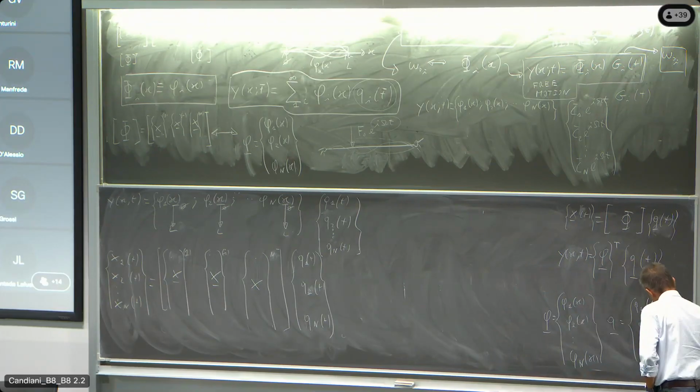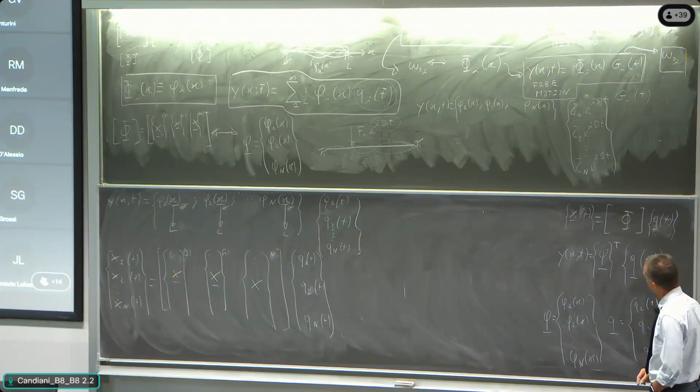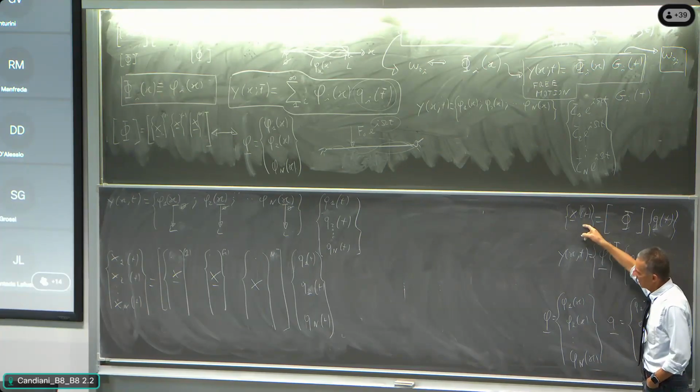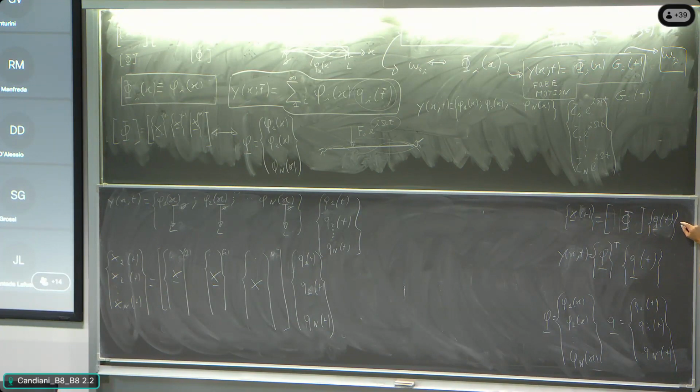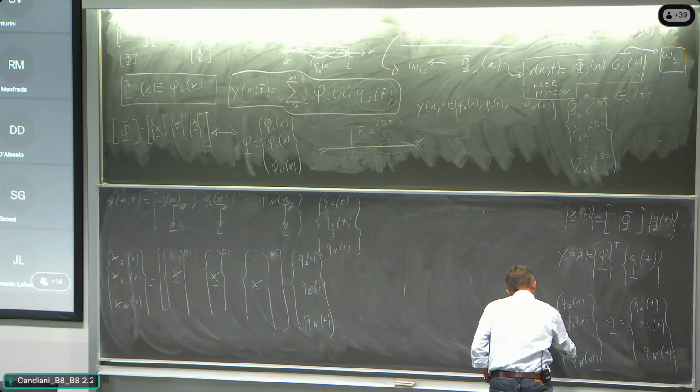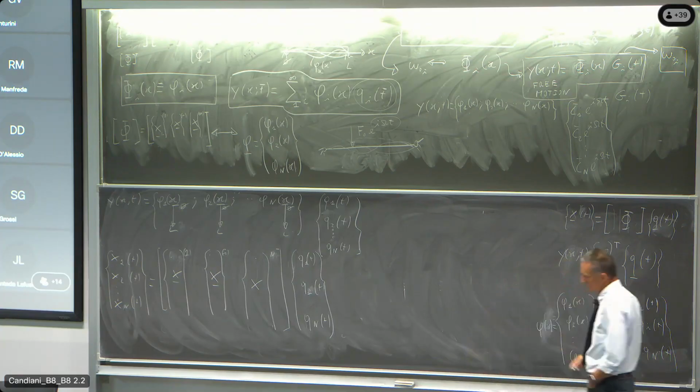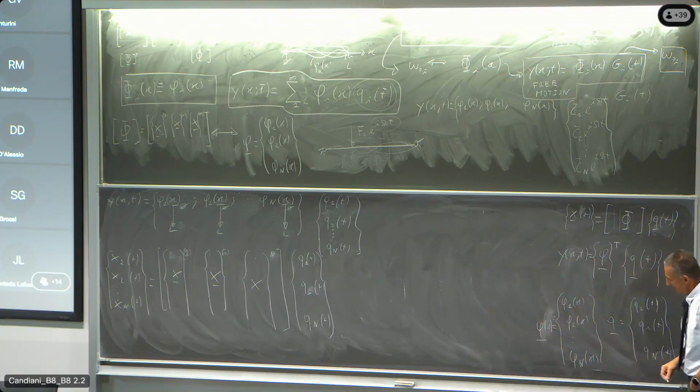so the tools with which we are playing are n degree of freedom, the vector of n free coordinates, the matrix of transformation, that is the matrix of the n eigenvector, the vector of the principal coordinate. Into the field of continuous vibration, we speak about the vector of the eigenfunctions, that is totally equivalent to the matrix of the transformation, the matrix phi.